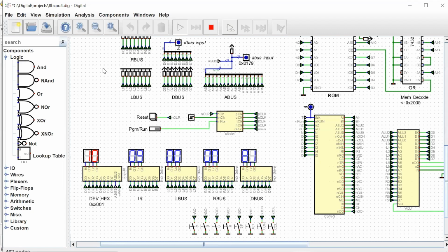Okay, so that's it for today. We saw how you can single step through the program with a manual clock, and we can observe what's going on. And we looked at how we could pause the running program. We can use the switches to inspect the register values. We didn't inspect RAM, but we could do the same thing by putting a RAM address in. And then we looked at a couple of our programs. We looked at the test harness, and we executed our very important test harness to validate our computer is functioning as designed.